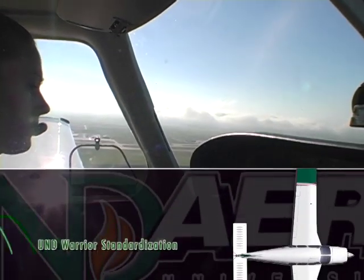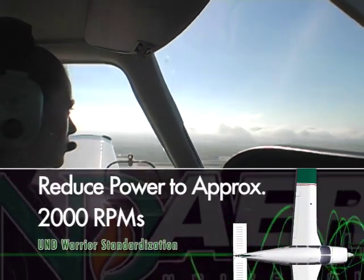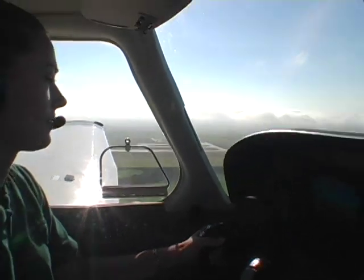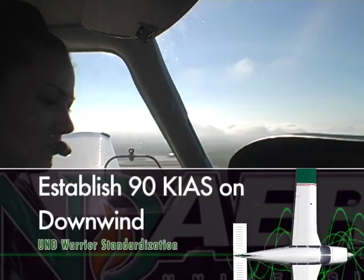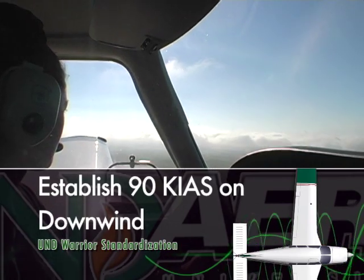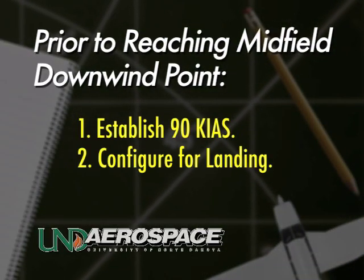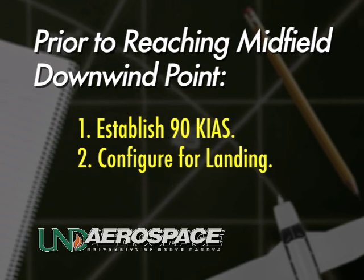So power should be reduced to approximately 2,000 RPMs, depending on atmospheric conditions, in order to establish the Warrior's downwind speed of 90 knots. If nothing else, the pilot should make it his or her goal to establish 90 knots and configure the aircraft prior to reaching the midfield downwind point.